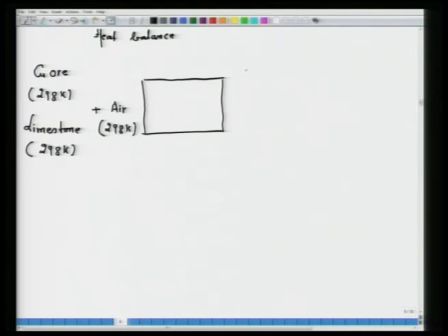Now, we have matte, I mean matte means Cu2S, FeS. So, in the matte we have Cu2S, that is equal to 200 kg, FeS, that is equal to 120 kg, and its temperature is 1400 Kelvin, that is important.